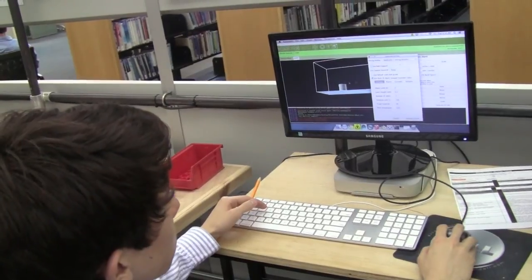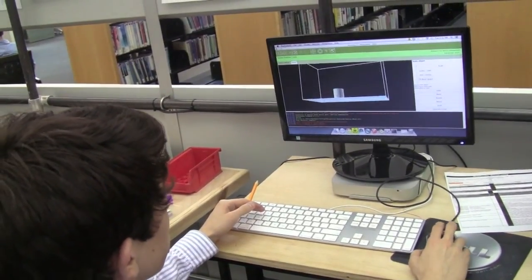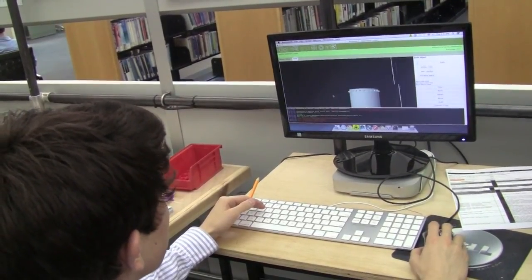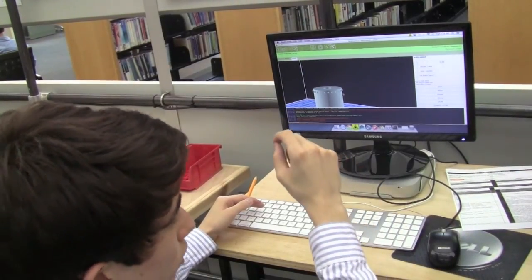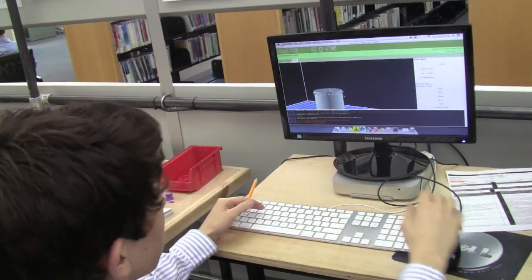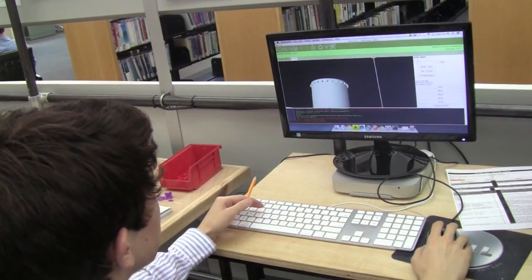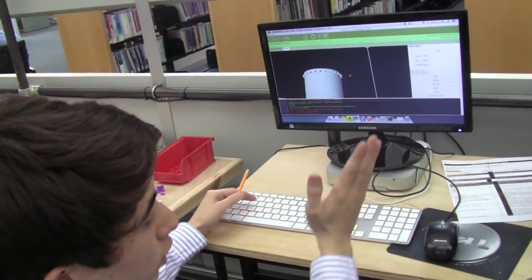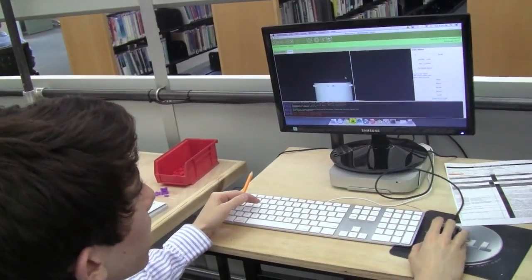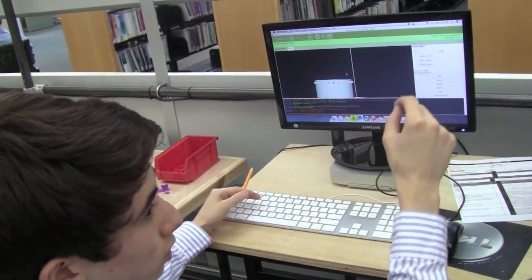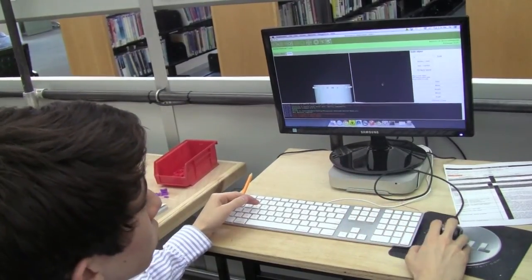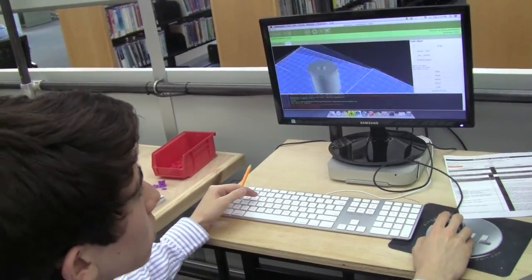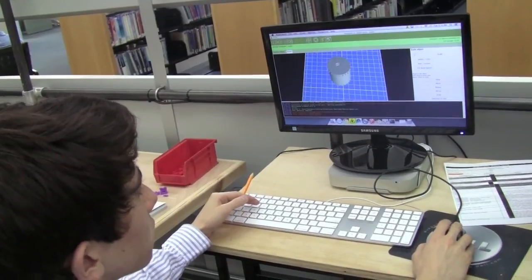And those small little points, so if I actually zoom in, those should be small enough and light enough that the printer can hopefully just move out a little bit and layer it. Although one problem I noticed is that this goes straight out instead of gradually angling upwards. If it angled upwards, then it could gradually start moving out. But because it goes straight out, that might go too far out that it wouldn't print. So that's actually an issue.